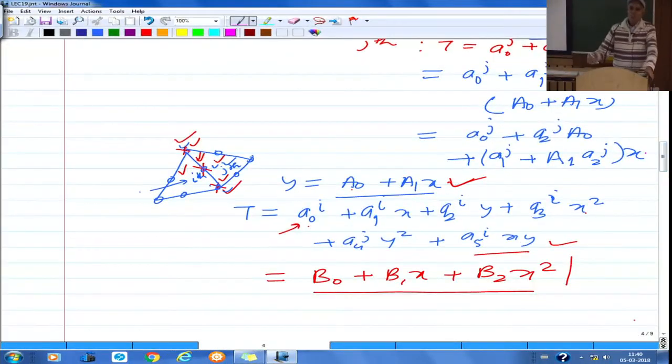So if you think of it like that, 8 noded gives you x cube, that is up to cubic variation of the temperature along the edge. If you add more number of nodes in this, you will find that the variation of temperature along the common boundary would always be of higher degree compared to the number of common nodes shared by the 2 elements along that boundary for a general quadrilateral.